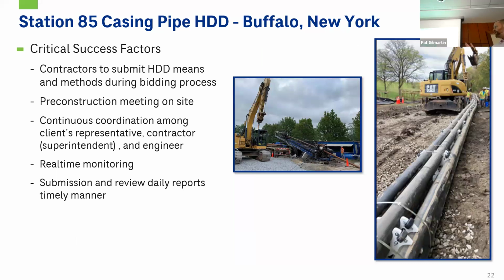So really the critical success factors for this one is we did have a pre-construction meeting on site, and you can see how these casing spacers are set up right here on the alignment, in order to discuss how we were going to be bundling these and how they were going to work through the rock. They did not have any major issues with getting through the rock. It was a little bit softer, though they did occasionally have a couple issues with chunks of rock ending up in there where they had to back out and drill back in. And that is part of the contingency plans that they submitted. So they didn't have any major issues associated with that.